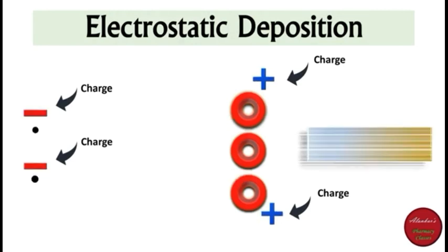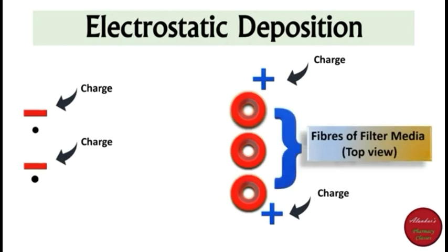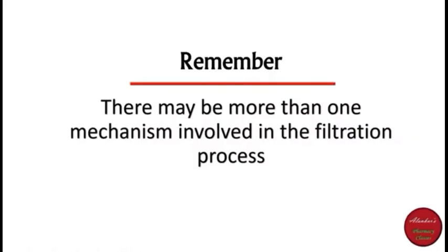Then next we see the equipments in centrifugation. The first equipment is the perforated basket type, and the principle of the perforated basket type is filtration. It is used for separating crystalline drugs like aspirin. Then next, the non-perforated basket type, and the principle of the non-perforated basket type is sedimentation, and it is used when deposited solids offer high resistance to flow.